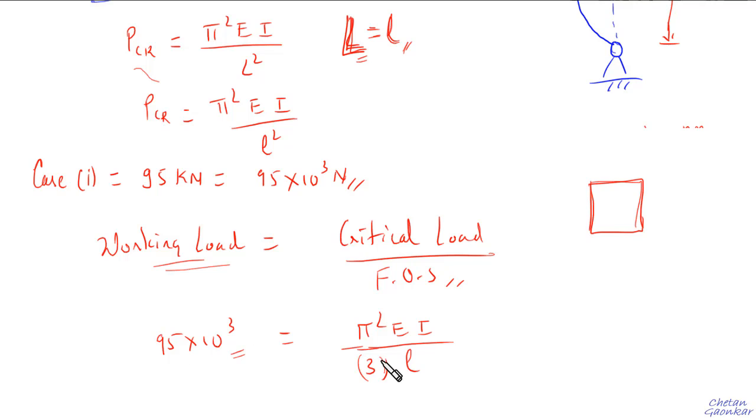So basically we know here everything. Now we know what is the value of E, which is given to us. We know L is 2 meters, so the only unknown is I, and this I will help us to find this dimension. If this cross section is a square cross section which is made up of, say, initially we'll assume it to be of dimension A, then how much will be the moment of inertia of this square cross section of dimension A?